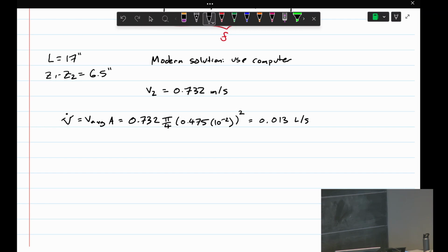So he asked a good question. He said, is the capillary effect involved at all? The capillary effect would be like, since this is a small tube, if I stick this in, we would expect a small rise, but this tube is already big enough that the capillary effect isn't really a factor. The capillary effect is for very small diameter tubes.